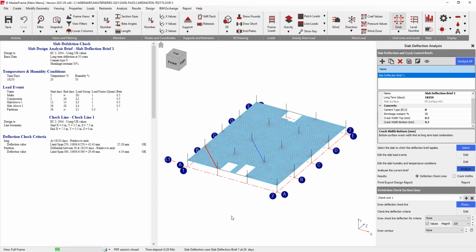That has the effect of redistributing load, producing more cracks. Also the creep coefficient, the compound creep coefficient at each step in time is calculated for each of the elements. That analysis is just completed in just under 20 seconds there, and it has done all of the nonlinear calculations. So with each time step, the nonlinear calculation is done until we get a converged solution, both in terms of deflections and crack stability.